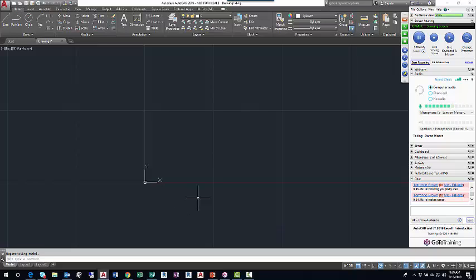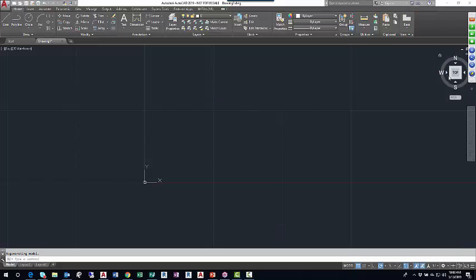You actually have a third coordinate, the z value, that is pointing straight at you when you're in a top-down drafting mode, which the symbol in the upper right corner of the drawing window can alert you to. That's called the view cube, and if it shows top, you're looking down on your drawing.